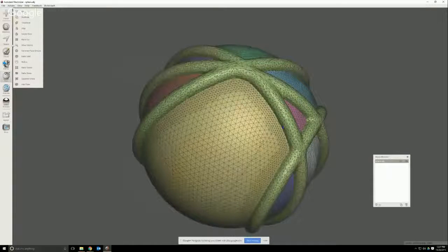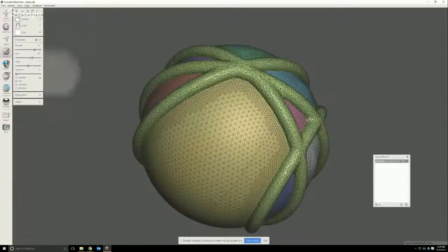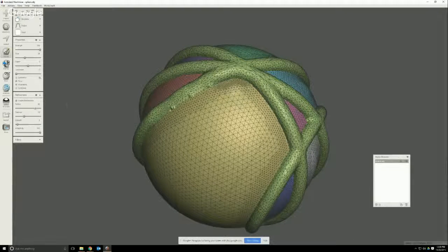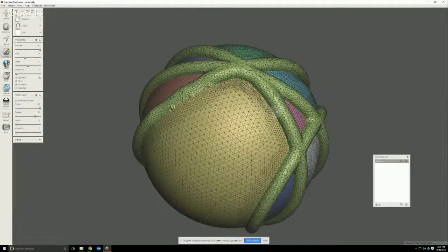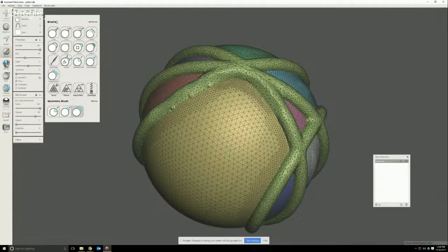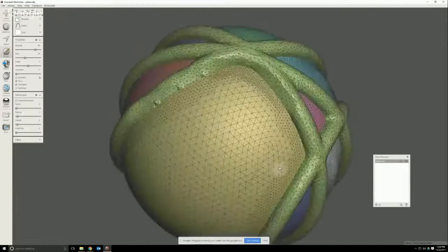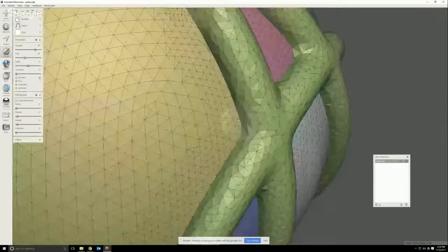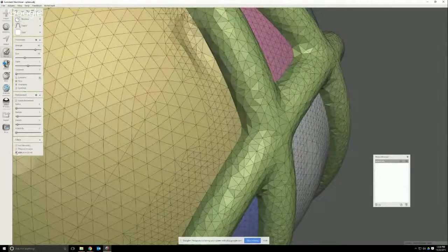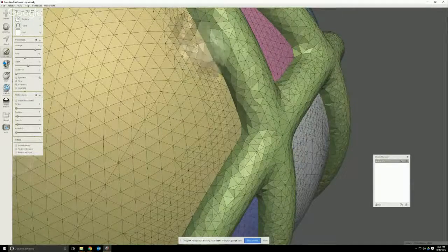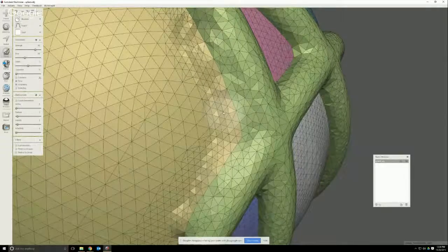I could go in with maybe a robust smoothing tool and start smoothing. Well, it's a little bit too big right there. Turn this on and start smoothing these out. Maybe not the robust smooth, but a shrink or bubble smooth. Actually, what I would probably do is a bubble smooth. Go over here, bubble smooth in, but I would do a control for, oops, my filter is still on, so I'm not going to restrict a group. So now that'll work. A bubble smooth out would do it really well.